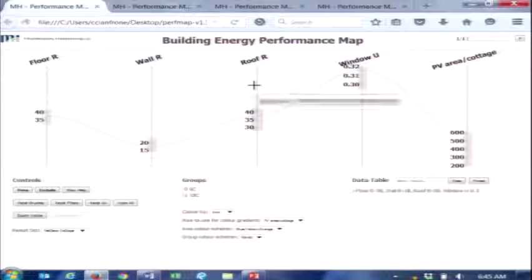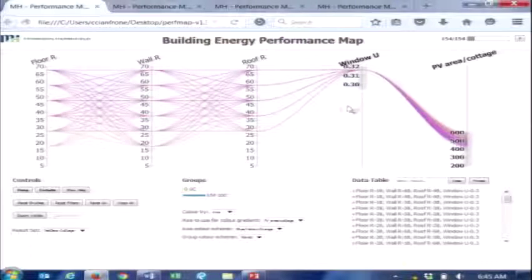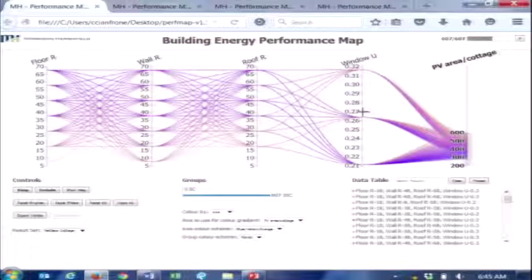And so this is a fairly simple example, but in an alternate situation, what would have happened in this project is, okay, great, it's got to be net zero, it's a design competition, let's just say we're going to insulate R60 walls, R100 roof, and you get these really not necessarily buildable, not necessarily cost-effective design solutions that don't necessarily make sense or may not be required. And so this allows you to look at all the possible situations and say, okay, well, what makes the most sense within this context? What is the most appropriate solution for this outcome?